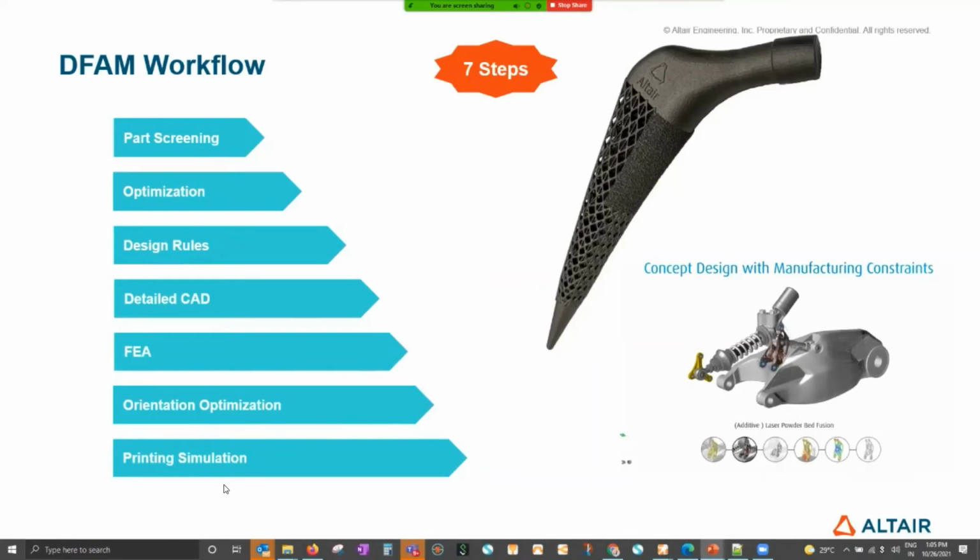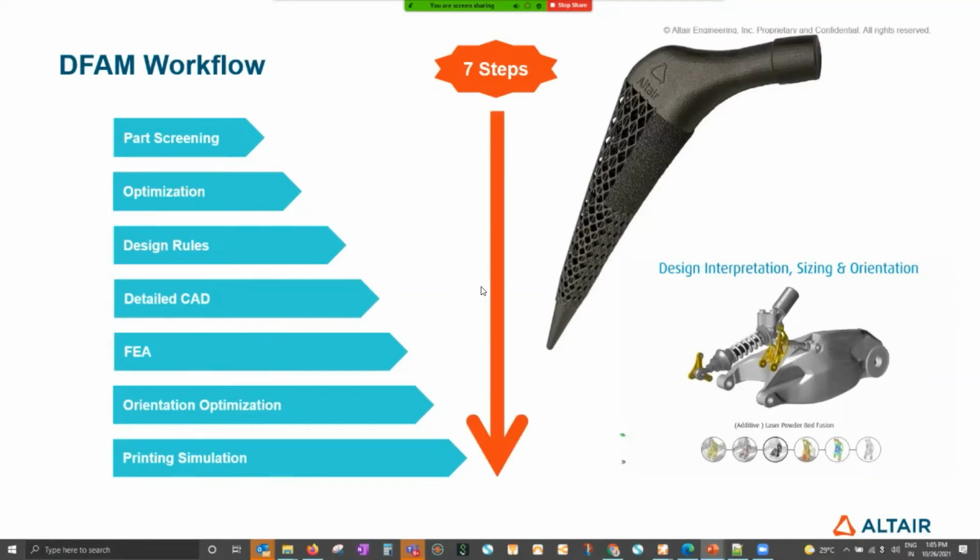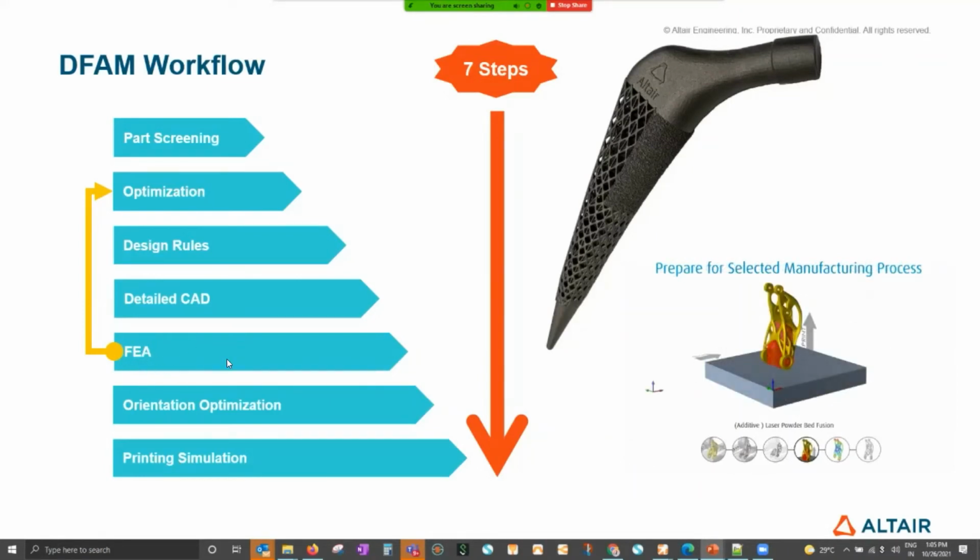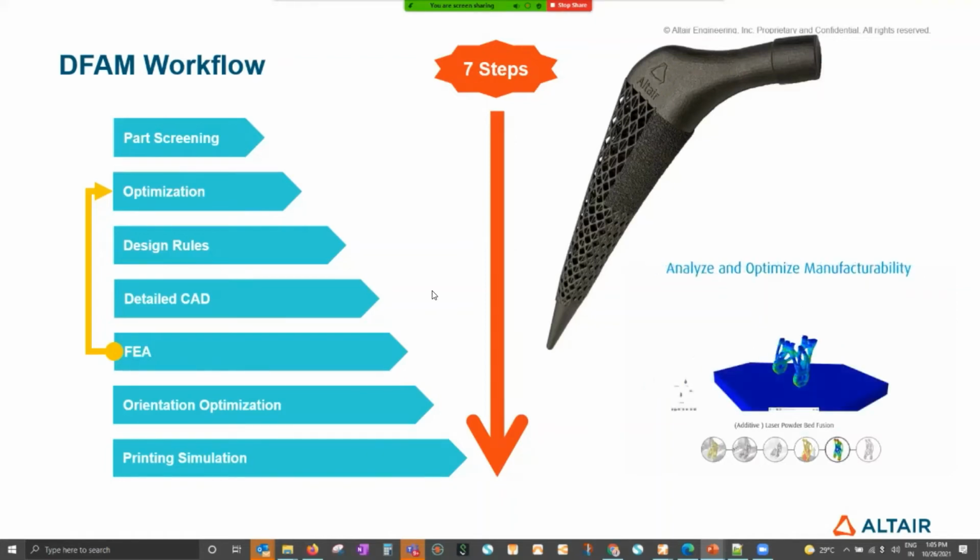However, these steps I have listed linearly, and this may not be the case. You may also have learning in different stages. Say in FEA, you learn that your structure is failing, or that your design is over-designed. That means your permissible stress is 250, you are getting say 900, or your permissible displacement is 1 mm, you are getting 10 mm.